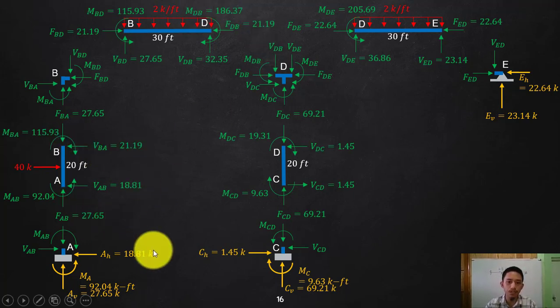So you can do this one, guys. Solve the shear. You can do that one since we had a lot of this. And if you solve that shear, summate, that should be equal to this. So we're good. Moment and then shear. Summate your shear, that should be equal to 2 times 30, which is 60. We are good. Solve your end shears. Summate, that should be 60 again. 20, 36, 23. It's good.